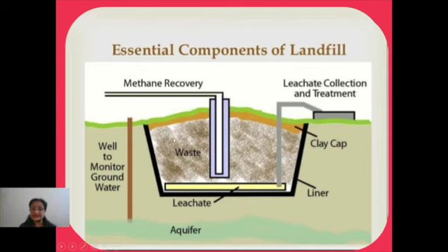The waste is dumped and it is always covered, right? And the lining is always made with cement, right? The base is always made in such a way that it is not going to seep down inside and thus harm the groundwater. So in that way it is safe.